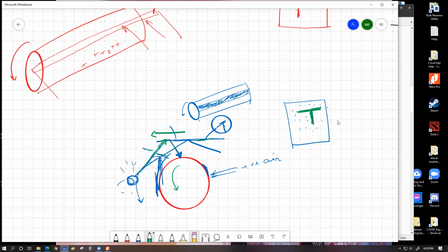But places where we do not have those things, we're going to have what? More reflection. White locations of the paper are going to do more reflection, and those strong reflections are going to fall onto this piece, and eventually for that strong light, the selenium atom or atoms will produce a free electron, and that free electron will neutralize the remaining charges on the drum for this section.